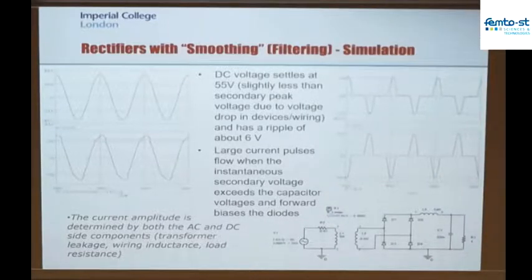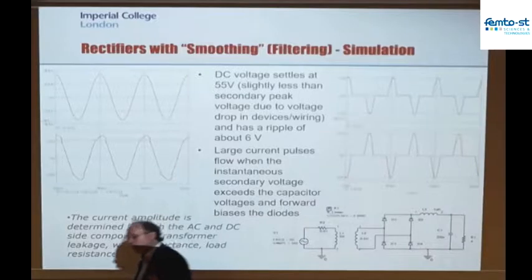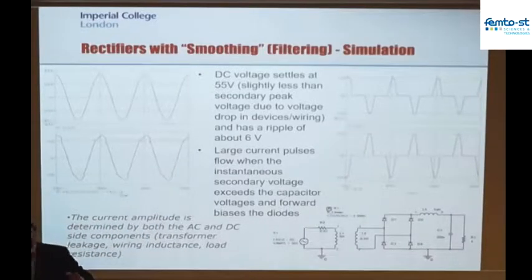And with the typical harvester, what I was wanting to try to do with the electromagnetic harvester was a set of waveforms which gave me a nice smooth set of forces, so that I had this nice linear damping. I wanted to ultimately have a force which was proportional to velocity. That's how I did all the analysis, and I wanted to then be able to control that force so that the force was proportional to velocity and I could dial in the constant of proportionality.